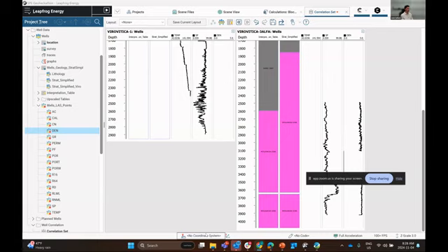And the same thing goes for units. So Leapfrog treats things as simply ground units. It doesn't read the difference between meters and feet or inches and centimeters. Again, we suggest that you convert everything to a common unit before you import into Leapfrog. Same thing for like Celsius and Fahrenheit. It just simply reads them as data points.